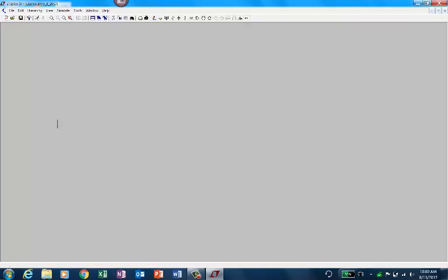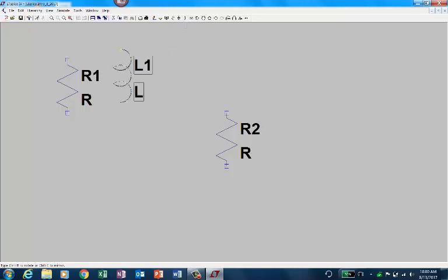With this, let us start by drawing a circuit. We bring a resistance here, one resistance, and we'll bring another resistance here. You saw that I just clicked the right mouse button to stop that one. I'll bring an inductor here and put it here. We'll look into how to organize them. And then we bring a capacitor. I'll bring a capacitor here, across that one.